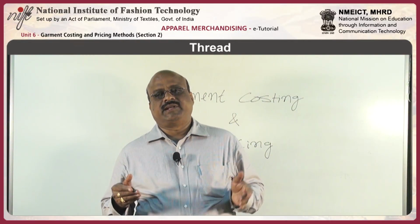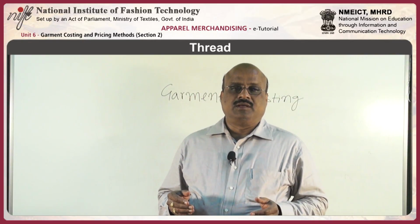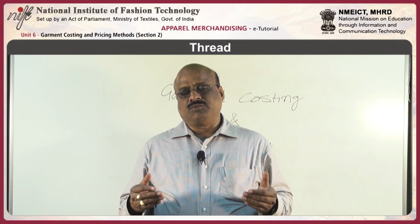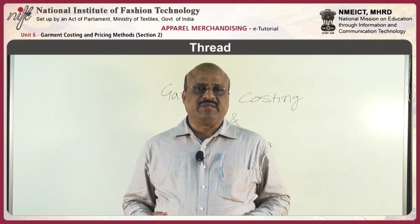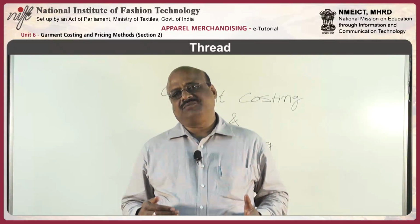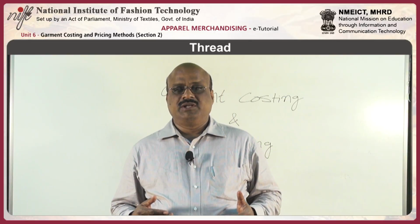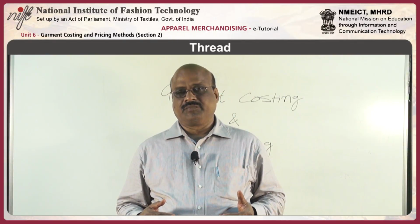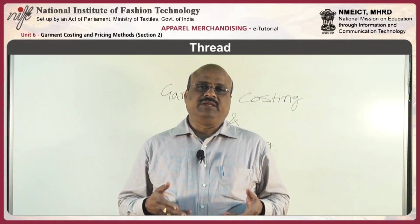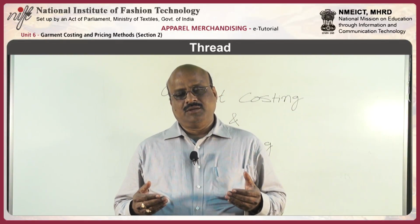Sometimes thread consumption can be computed while preparing the sample. When the export house or the garment manufacturing unit is making a sample, thread consumption can actually be calculated while making the sample itself. So the initial weight of the thread cone is measured. They will weigh the initial weight of the cone, and once the sample is prepared,